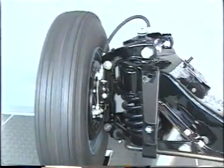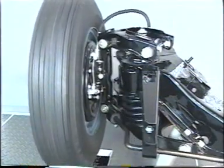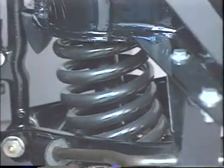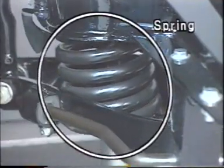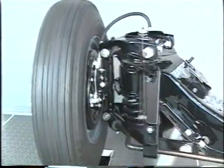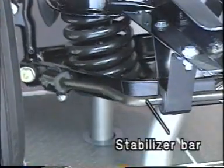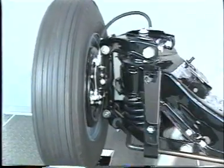There are various types of suspensions. Here, let's take the double wishbone type as an example to look at suspension components. The spring dampens the shocks received from the road surface. The shock absorber improves riding comfort by restricting the free oscillation of the spring. The stabilizer prevents the vehicle from rolling, and the suspension arm holds the wheels in the proper position.